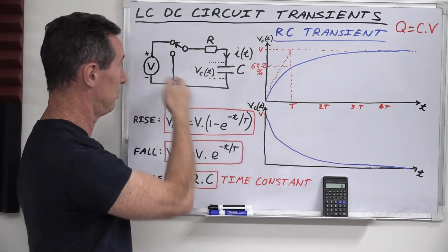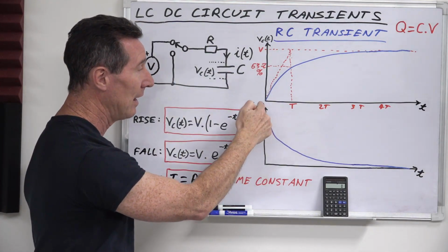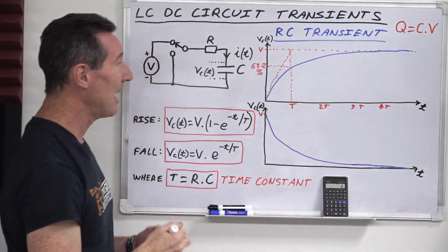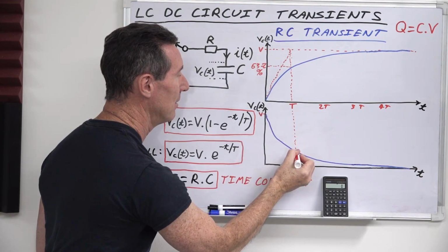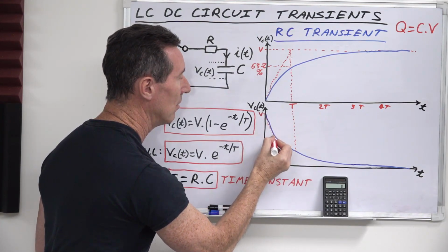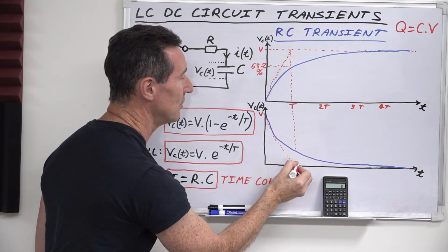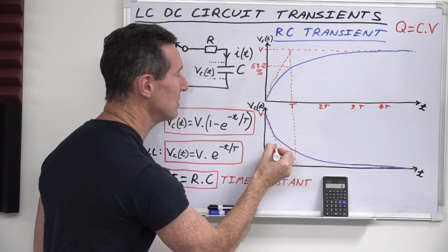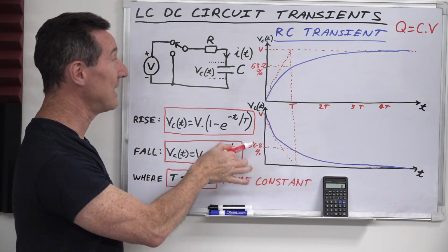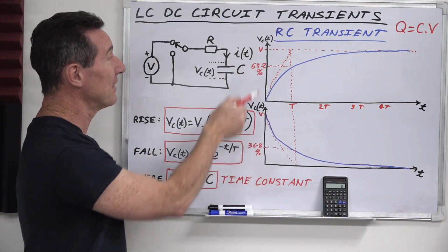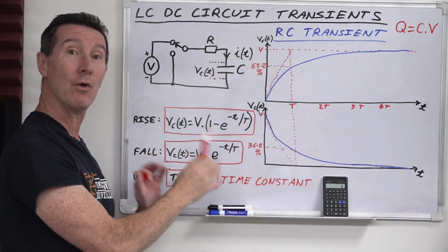If this is 1 volt, it starts out at 1 volt, and then it discharges like this. And once again, the time constant is exactly the same thing. If you follow that curve, trust me, you'll get to a value of 36.8%. Once again, if you see that figure, either of those figures, you know you're talking about LC or RC time constants.